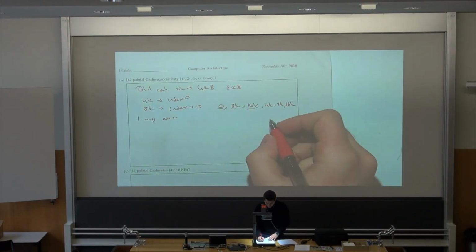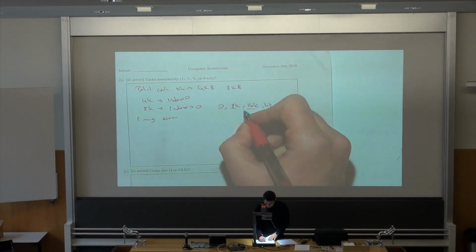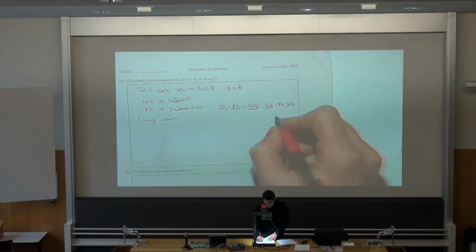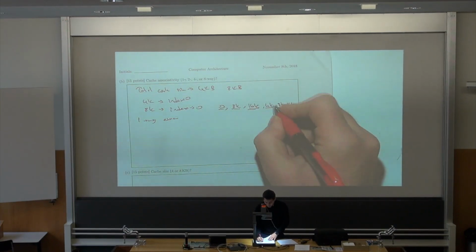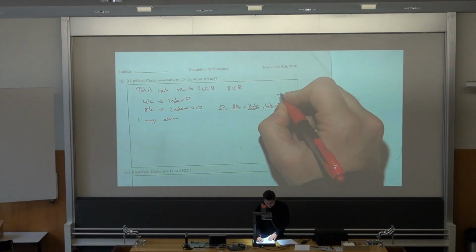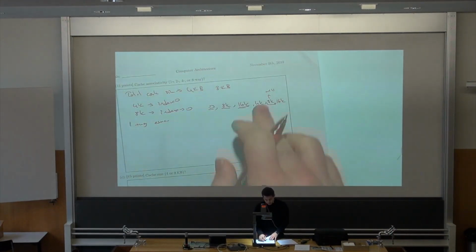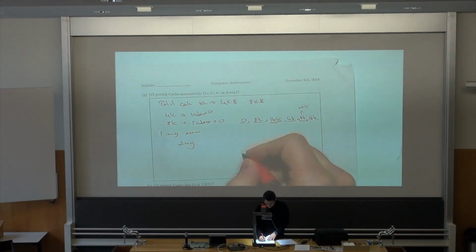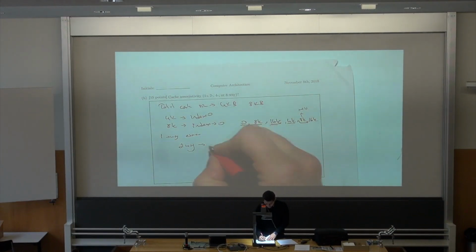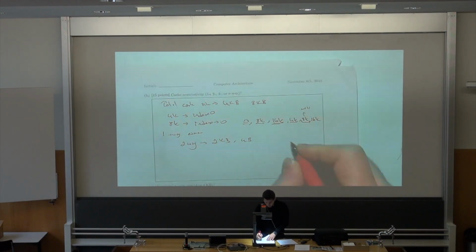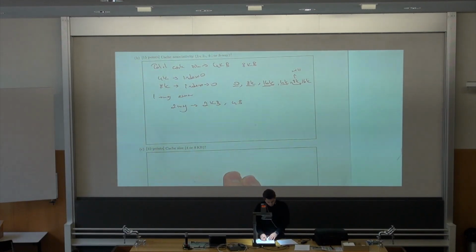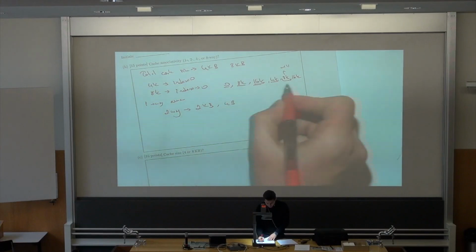So basically, when I access 8K, it will be replaced with this one, and 16K replaced with this one, 4K. And again, when I access the 8K, this will be a miss, and then I will replace 4K and put the 8K. So let's imagine two-way. Then the ways are either 2 kilobytes or 4 kilobytes, right? So I'm going to consider all the accesses of the multiples of 2 kilobytes here. Again, I'm going to do the same thing that I did here.